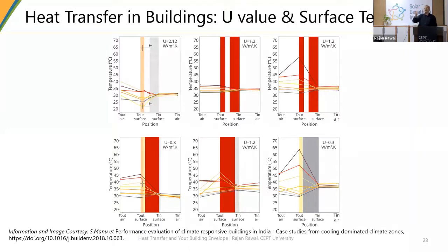That is primarily because of the cavity inside. You have a 4.5 inch thick brick wall, you have about 50-60 mm of air gap, and again, the air gap in one of the cases is ventilated, in another case it is not ventilated. So again, how your cavity is functioning will matter.